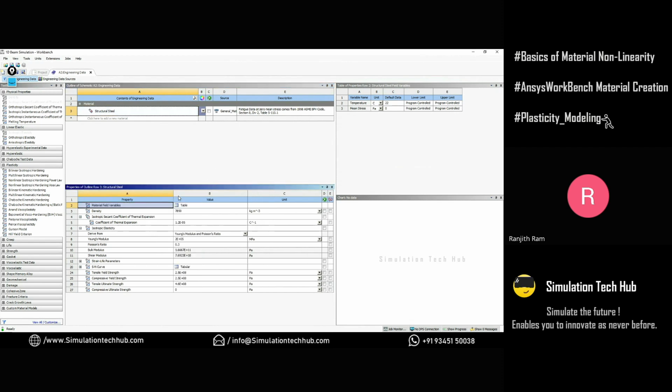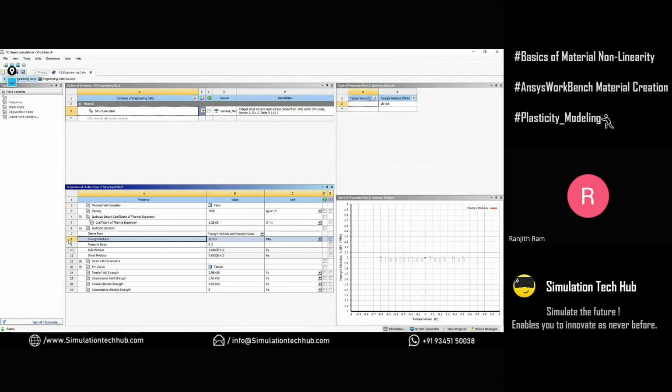Other than that, in linear there are no other properties, only two inputs: Young's modulus and the Poisson ratio. Young's modulus tells you the stiffness behavior of the whole material. Since it's an isotropic material, that's the only input. Poisson ratio gives the lateral to longitudinal deformation ratio. Other than that, there are no other parameters. Shear modulus and bulk modulus are calculated based on the Poisson ratio and Young's modulus.